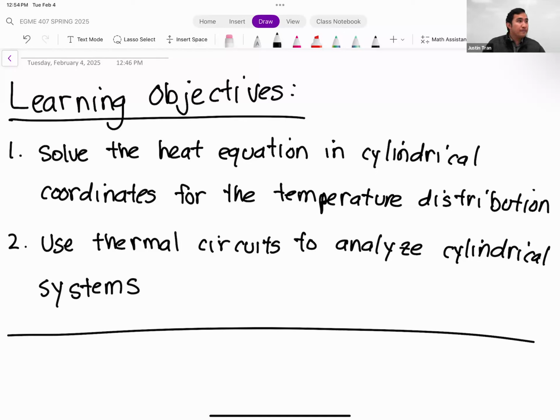I have a couple of minutes before I ask you a question. Sure, of course. The homework question. Can you just let me know if this graph is relatively right, what I'm thinking? If it starts at a higher temperature and it's going to a lower temperature, then it would be going down. Yep. But since the area is closing, it means it's going to go at a slower rate. Right? So that would be true if there was any production on the inside, but here you just have a fixed temperature here and a fixed temperature here. So it would be constant? Yeah, like a constant slope?